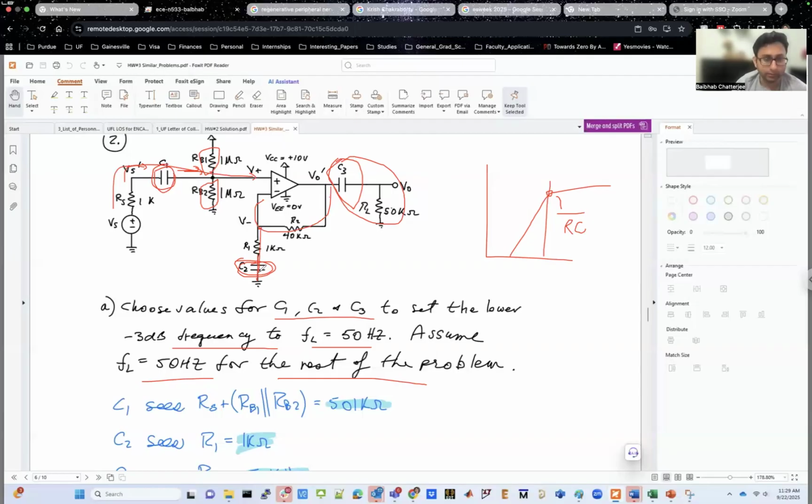That has to be there. Unless that is there, it's not a non-inverting amplifier. So for the non-inverting amplifier to exist, the frequency has to be high enough, because unless the frequency is high enough, C2 is not a short. So this is also a high-pass filter because it only allows higher frequencies to pass through the system.